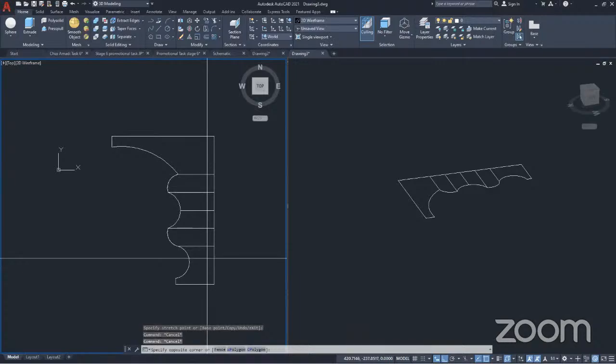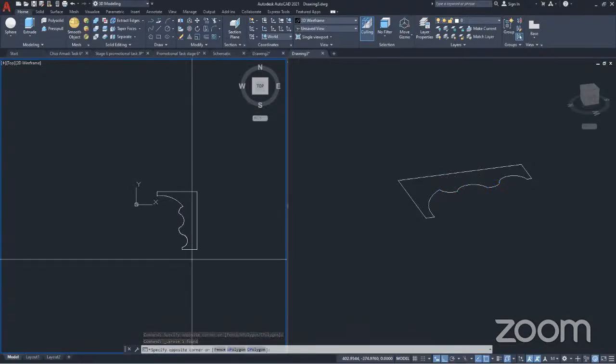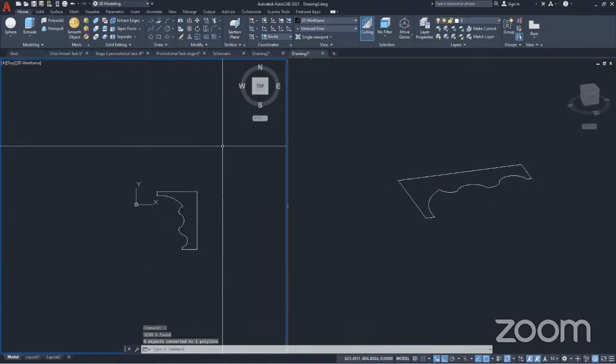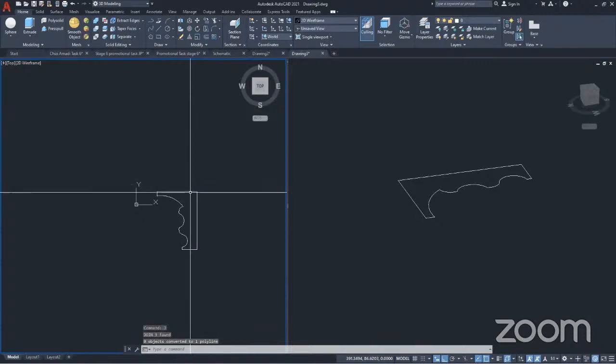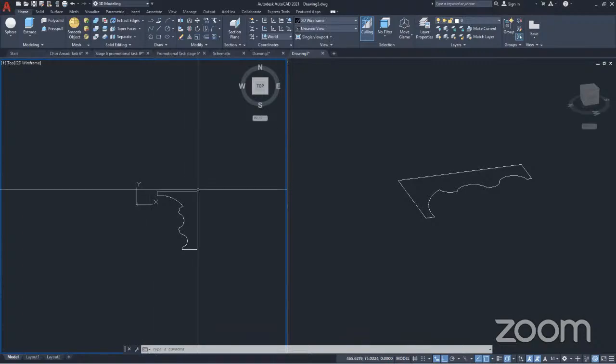Now we want to make a stool from this. First of all, we need to take off unwanted parts and then do a join. Look how I do the join to this, not the center line. J, join it. Now if you move around it, you see it's just a single entity. Okay. Now I will just need to use my revolve tool. Then select what to revolve, in this case, this geometry. Enter and use this as my revolve axis. And then I type in 360.